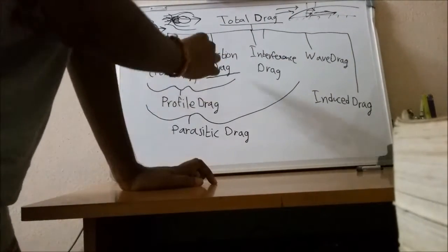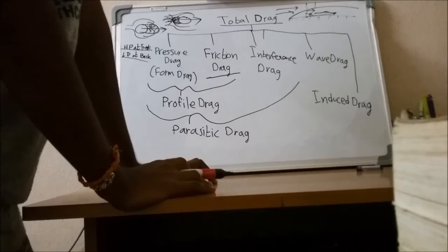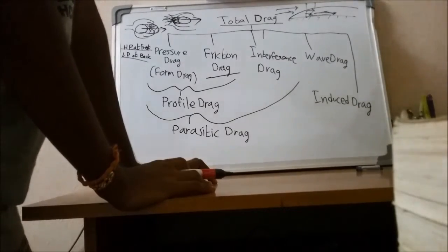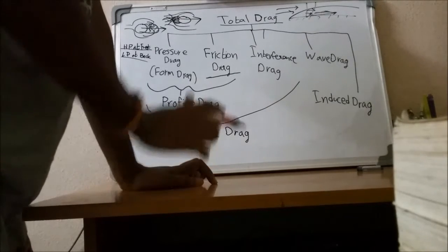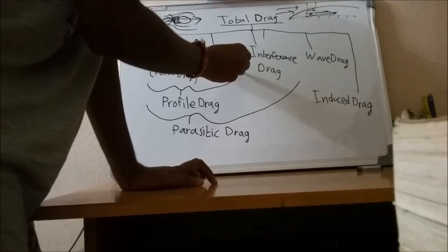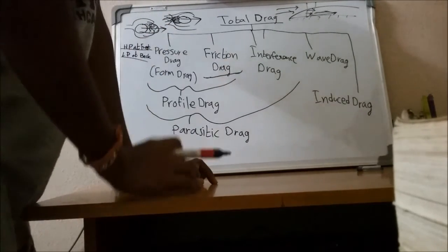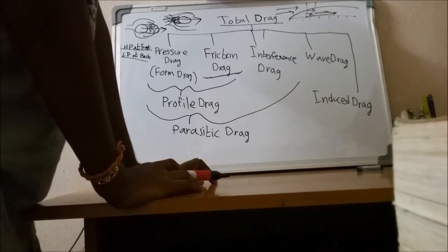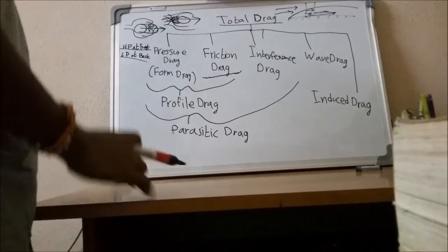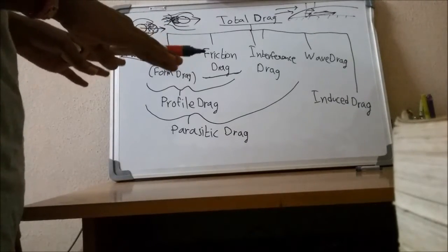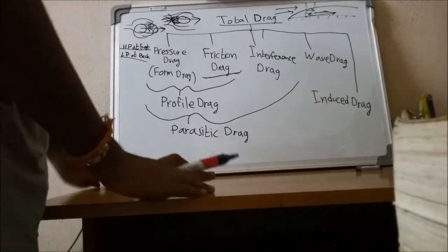This is what is known as friction drag, and it depends not only on the boundary layer but also on the surface roughness. This is very important if you are trying to design a swimming suit or something like that, because the material you use greatly influences the amount of drag induced on the swimming person.